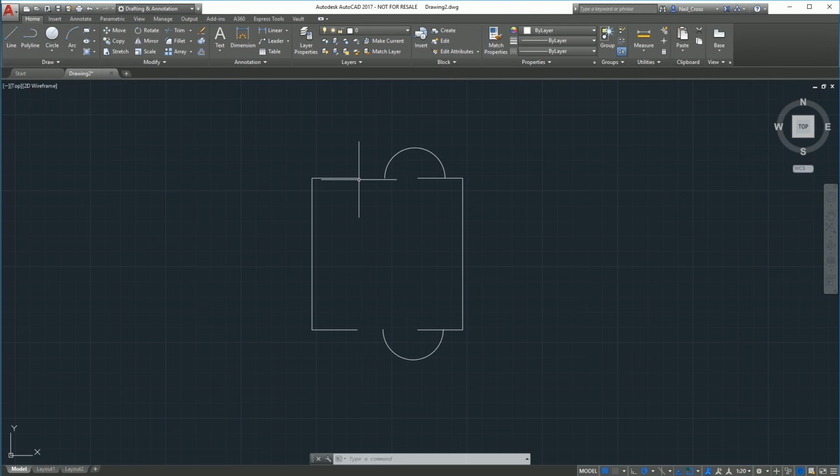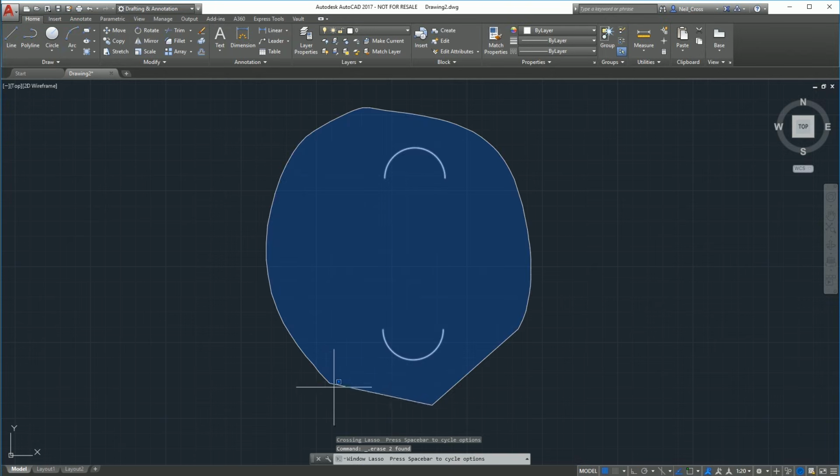Similarly, that line here stops here. You see there's now a break between the top edge of the rectangle or the square and the end point of the arc. Well, you can place a 2D constraint in Inventor to always keep that point there touching that point there. So that'll never cause a break when you move objects around. So back in the olden days, we just didn't have constraints, but nowadays we do.